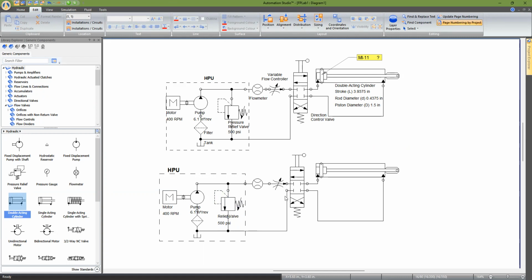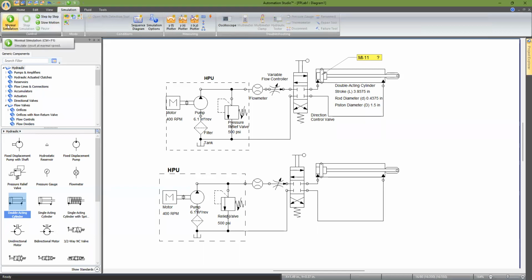And as the final step, that would be our simulation there. We want to run the simulation by going to the simulation tab and playing a normal speed simulation. And from the simulation, we want to gather certain experimental data. Once this extends, we want to know how fast it is extending, or how much fluid is passing through, and so on. The other variety of parameters that we can actually extract from a simulation.